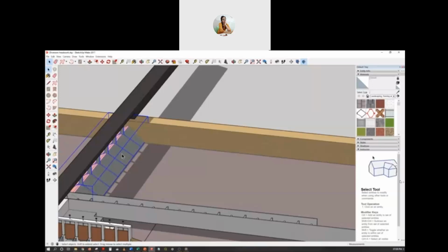Now, this portion is called a fish ladder. It's a long channel connecting the upstream and downstream of the weir, and it is provided with these kind of small walls projecting from both sides of the canal. What happens is, water, when flowing through this, will have to take a very zigzag path like this.